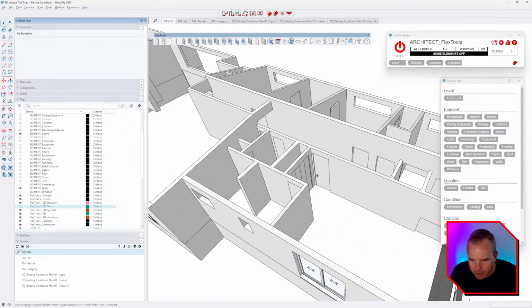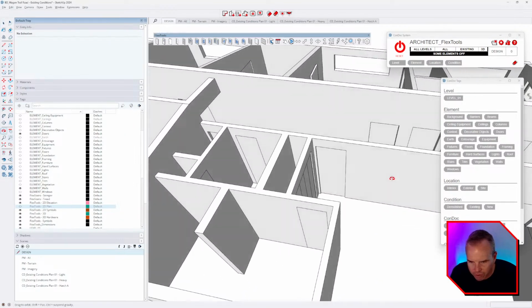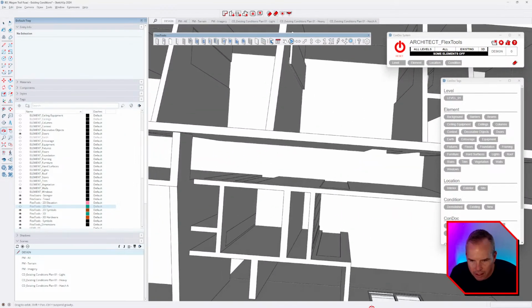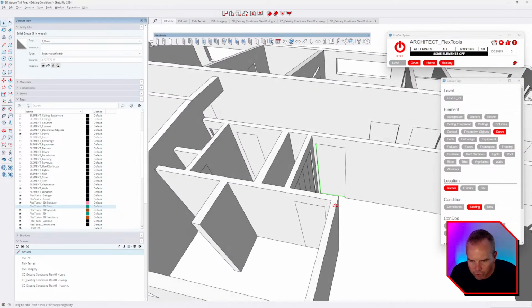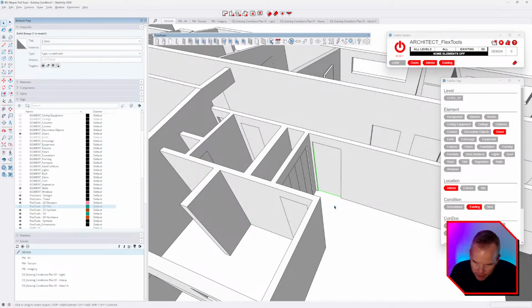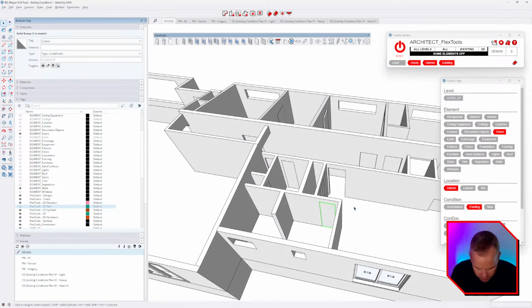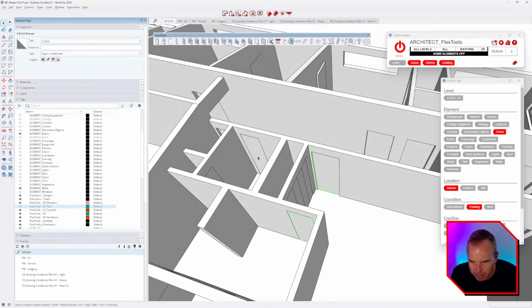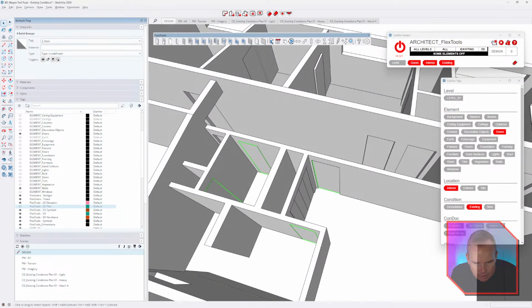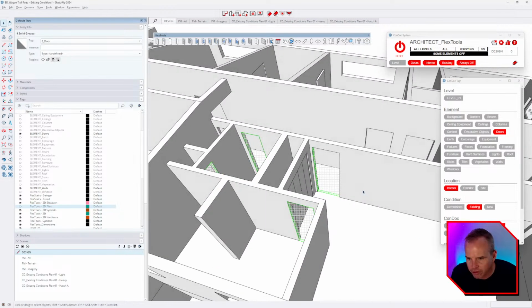That looks good. All right, so now we can keep using our flex tools, and we're gonna stick with it. You could make the argument that some of these interior doors are very simple and perhaps don't warrant flex tools. Also, when you're deleting these doors, you could choose to leave them always off if you're just not sure.